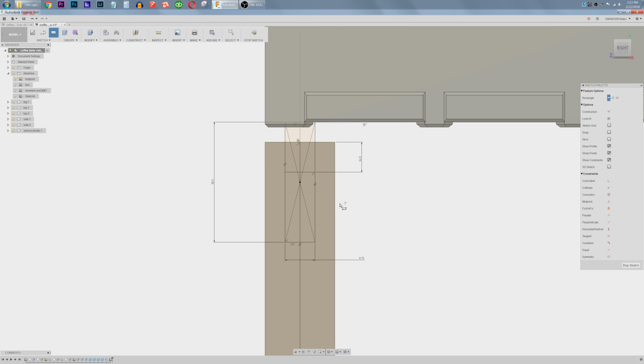And we need another R for rectangle, center rectangle on this center line inside this rail. And this is going to be the mortise and tenon part. D for dimension from here to here is exactly 0.25 inches. From here to here, 0.25 inches. This is all stuff that takes a little while to figure out, but I've already got this in my head, so I'll save you guys the slow contemplating process here.